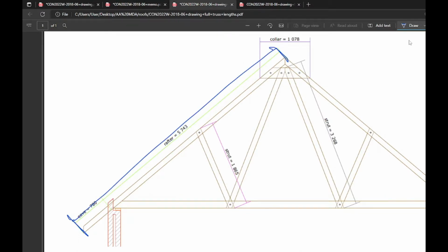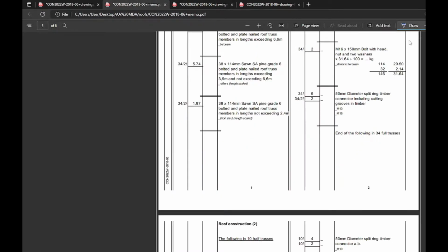Again, this has been scaled, so we'll go over to this one. In the event that you're not given any of these dimensions, you'll just be given a diagram of the truss and a section scale. You'll take your ruler to the furthest point as indicated here, including the shaped end. You take it past, right to the corner, and then with your ruler you measure right to that corner as well. In this case for the shorter strut, she's gone to this furthest point, that corner, and this furthest point, that corner. She's used the ruler, converted it to millimeters, and came out to 1,870 millimeters.